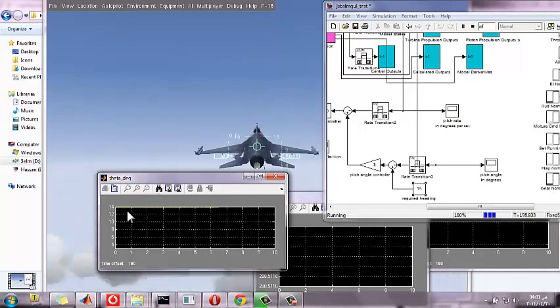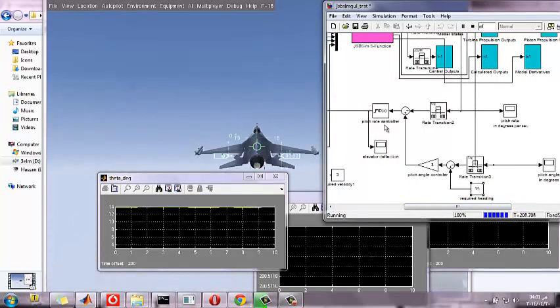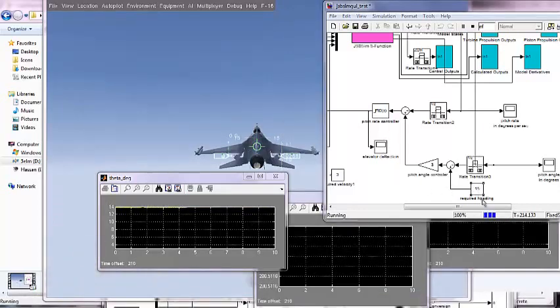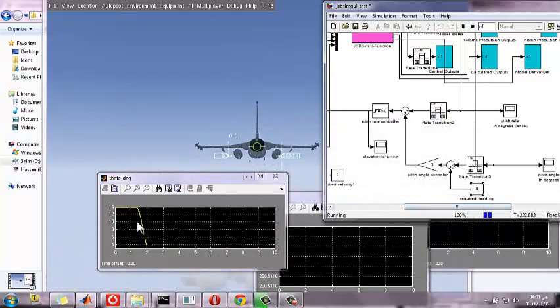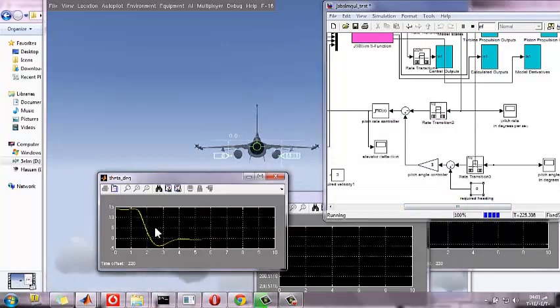And also we can notice that it keeps about 14 degrees with 1 degree steady state error, which is acceptable, regarding also that this controller was designed using sense only, not any accurate numbers or calculations. Let's change it back to 0, for example. You can see that this angle drops down in a simple lag manner, and it keeps almost 0 angle.